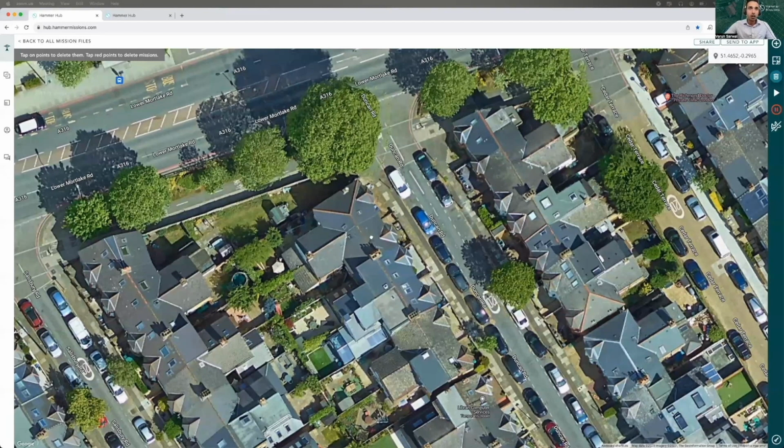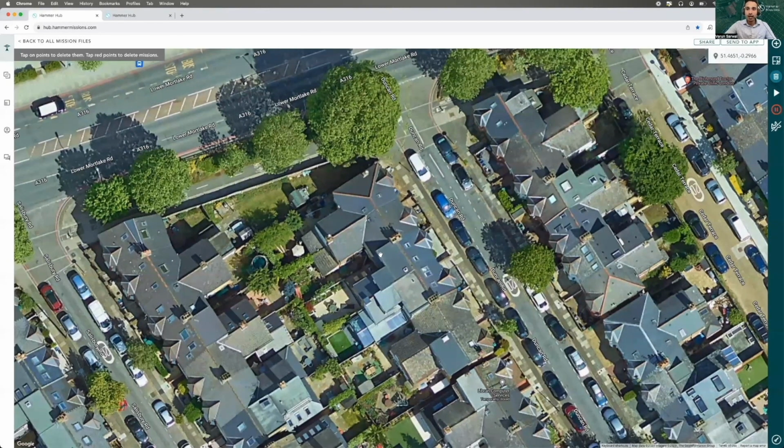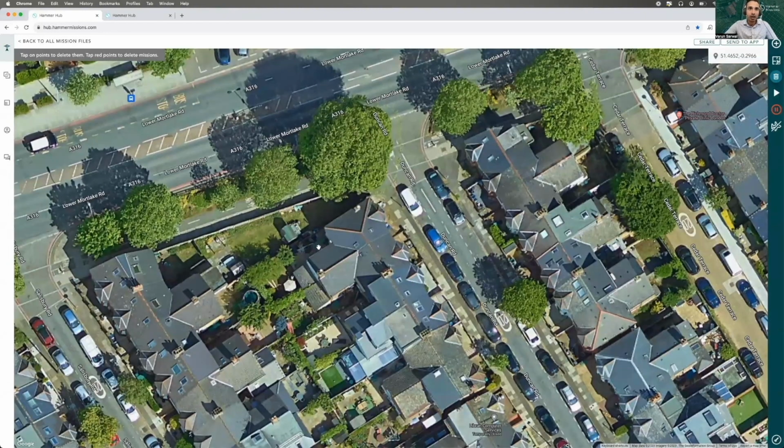Right, so hopefully you can see my screen, and in this particular video we'll be going over how to capture this particular residential roof in thermal and visual data and model that using drones. Specifically we'll be looking at the Mavic 2 Enterprise Advanced and the Mavic 3T drones, and how you can take all of their images and use that to create a map of the roof, and use that as a basis for measurements, as a basis for inspection, and create deliverables for your end customers.